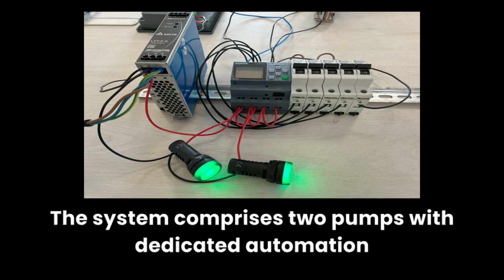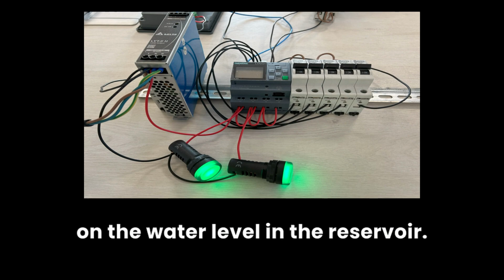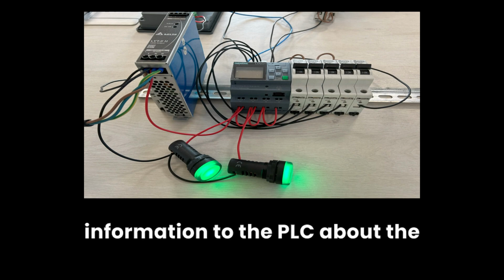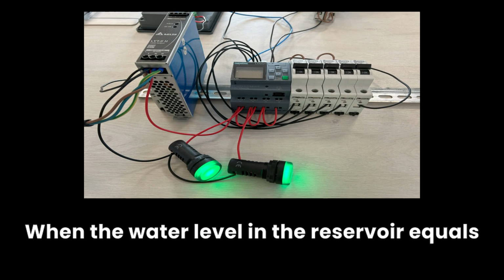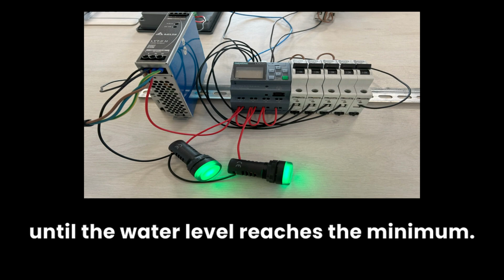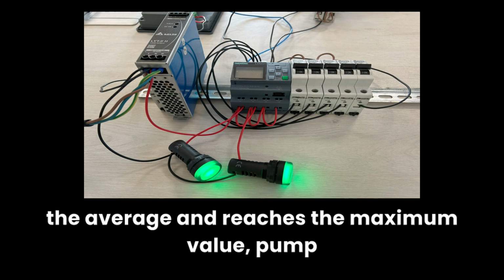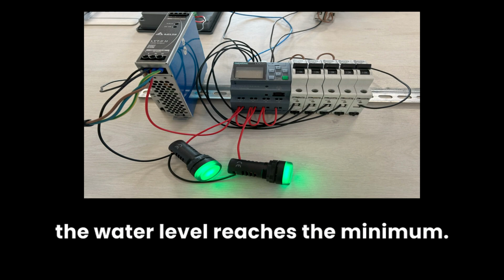The system comprises 2 pumps with dedicated automation that ensures the pumps are activated alternately based on the water level in the reservoir. The reservoir contains level sensors providing information to the PLC about the minimum, maximum, and average water levels. When the water level in the reservoir equals the average level, pump 1 starts and operates until the water level reaches the minimum. If the water level continues to rise beyond the average and reaches the maximum value, pump 2 is activated, and both pumps operate until the water level reaches the minimum.